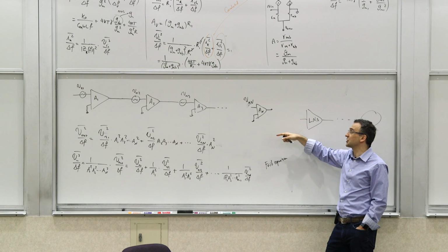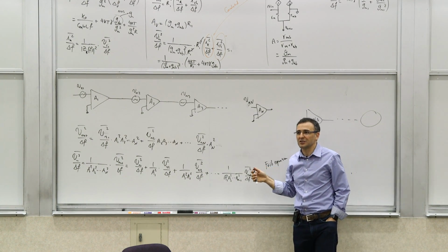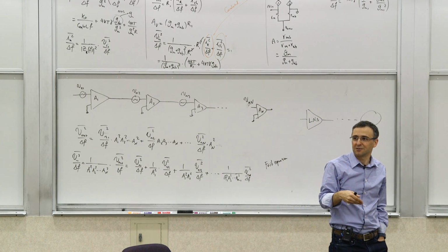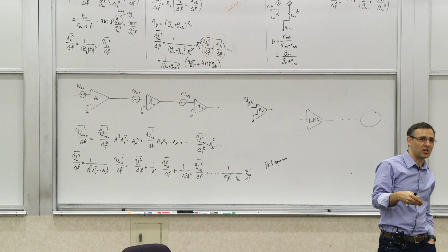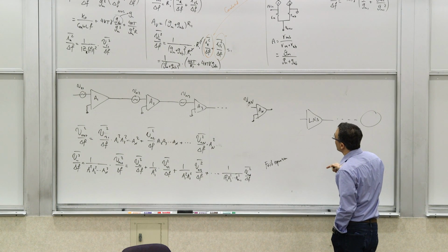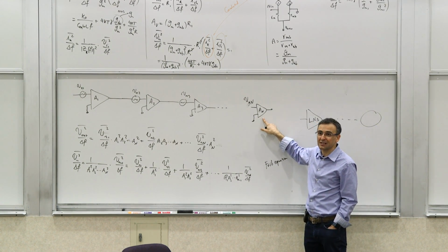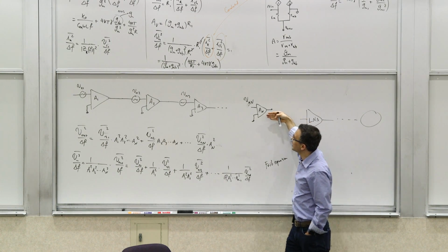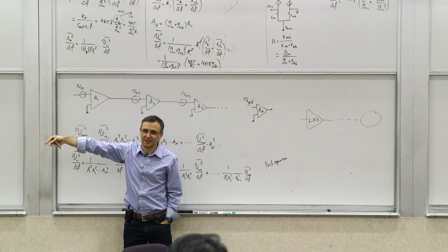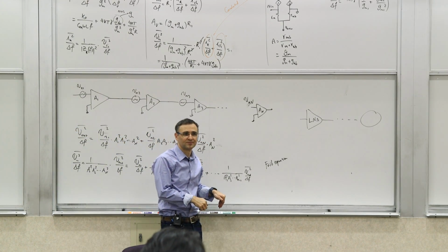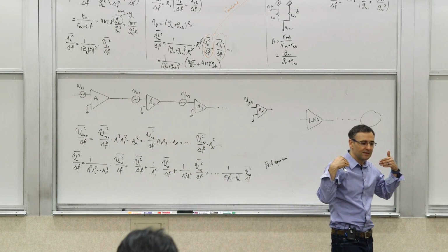For example, when you're transmitting, it's the nonlinearity of the power amplifier that people talk a lot about, because that's a transmission chain. Or even if you're receiving, the nonlinearity of the last stage matters, because that's where your signal is the largest. So nonlinearity goes in the other direction in significance, and noise goes in this direction. So that's one way to think.